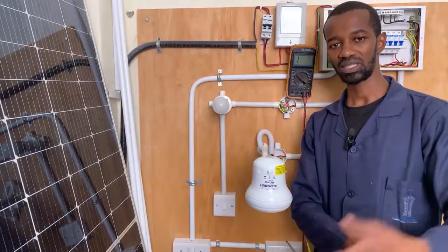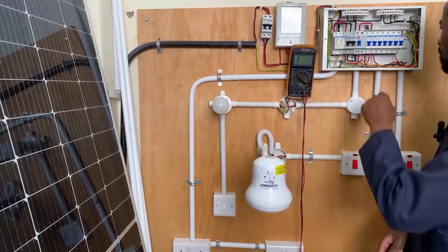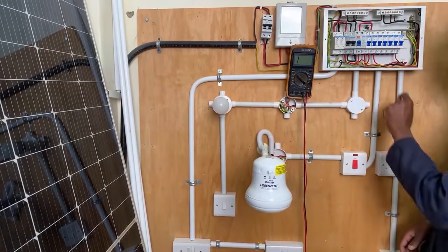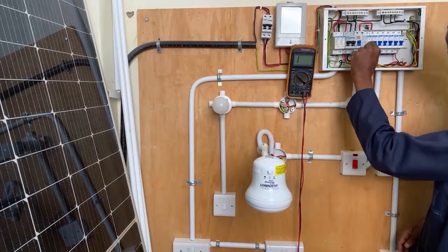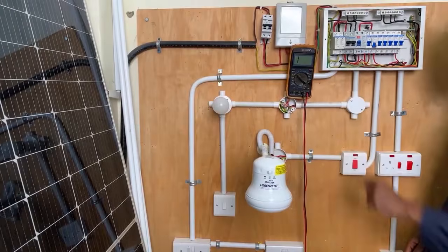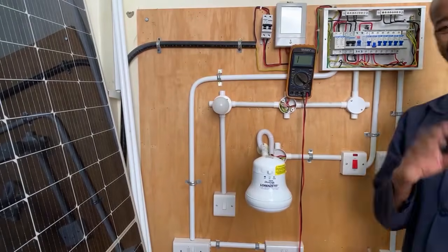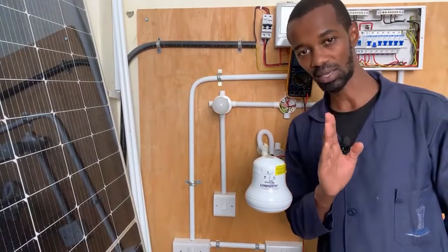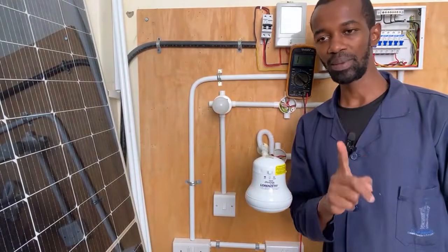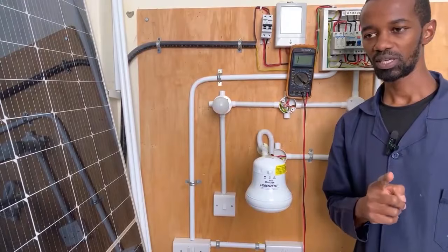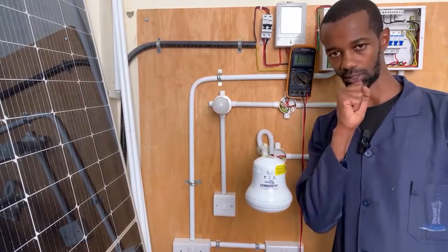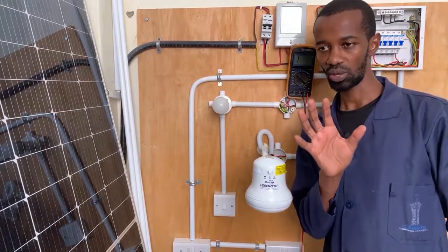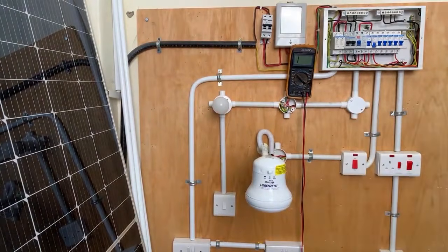You go circuit by circuit, assuming that the same problem happened with this. You see, you have a cooker unit here. It is supplied by this MCB. You go to a customer, you find that there is an MCB that has tripped. In most cases, you'll find that a specific circuit has a problem. Only one MCB will have tripped. If that circuit is the one that has an issue, you now narrow down to that circuit. You ensure that you only solve it.